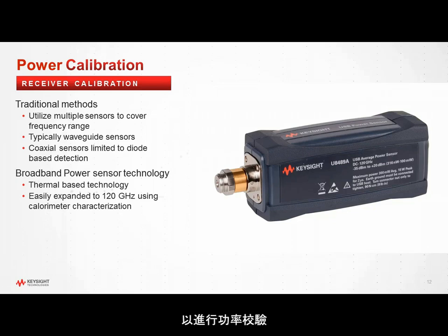system for power calibration. What this allows you to do is not only do traditional S-parameter measurements, but then opens it up to things like gain compression, intermodulation distortion, IMD type measurements, spectrum analysis, harmonic measurements, and so on. So you would see this in the demonstration where I show you the amplifier measurements, and having a power sensor like this forms a critical part of ensuring accuracy in your measurement and its quality.